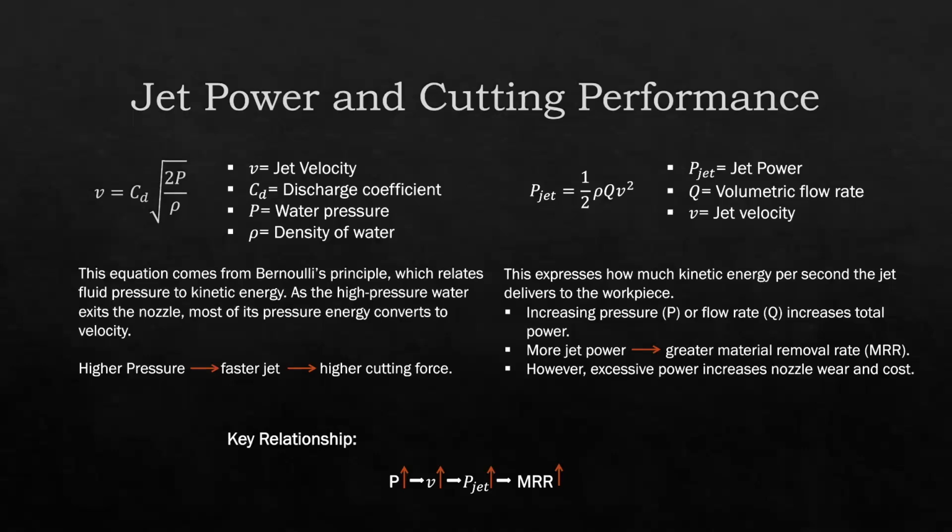But there's always a trade-off. Higher power also means more nozzle wear, more energy use, and higher costs. So the goal in real applications is to find a balance between the cutting speed, the precision, and the efficiency. And then moving on.